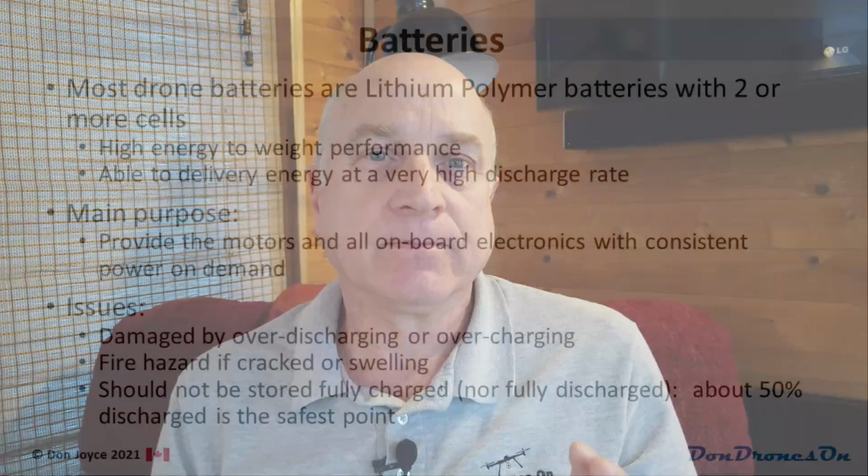Now here's where it gets tricky. Since over-discharging or overcharging can occur for a single cell within a multi-cell battery, it is important to frequently check the balance of your individual battery cells within a pack. The DJI apps include this capability. Oh, and never attempt to charge a frozen or very cold battery. Let it come up to room temperature before putting it on the charger.